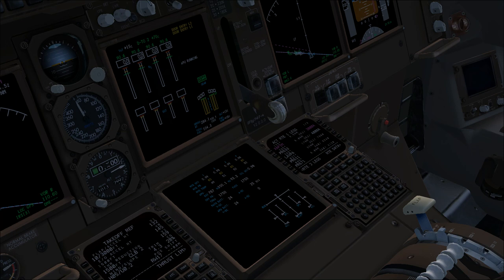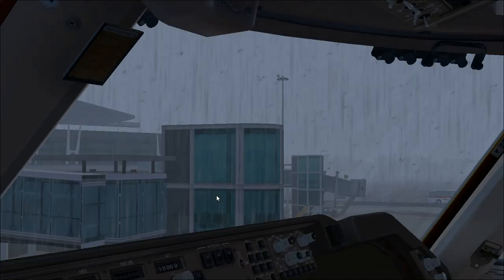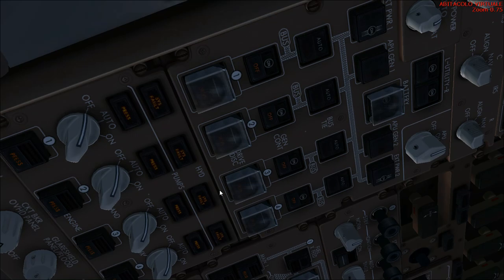and then we will connect the APU to the onboard systems to give the power. The EGT now is increasing again. Now it should start decreasing, and when it stabilizes at 400 to 500 EGT, we will have the available lights coming up on the APU Gen 1 and the APU Gen 2. Waiting for that, just some information for you.